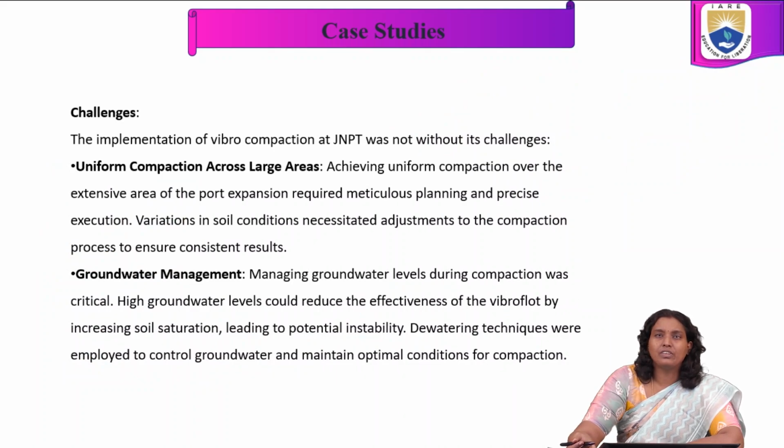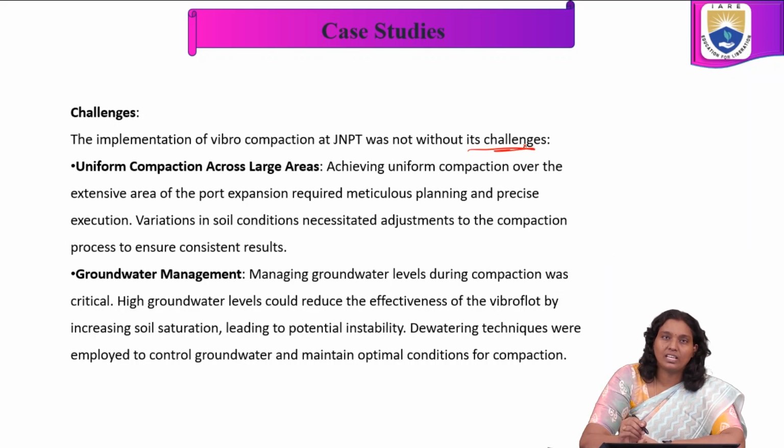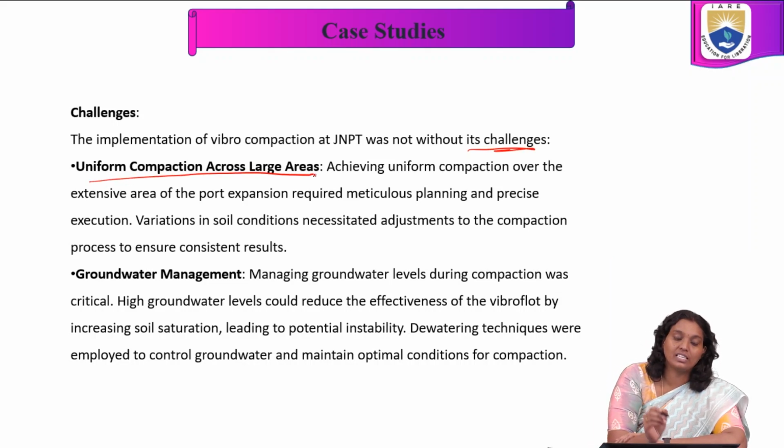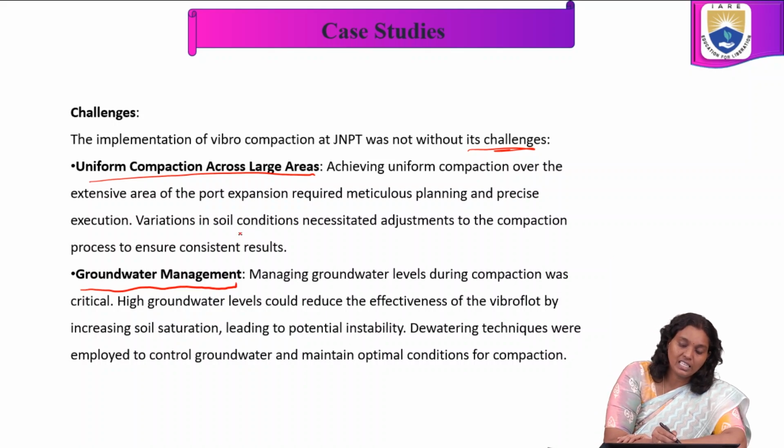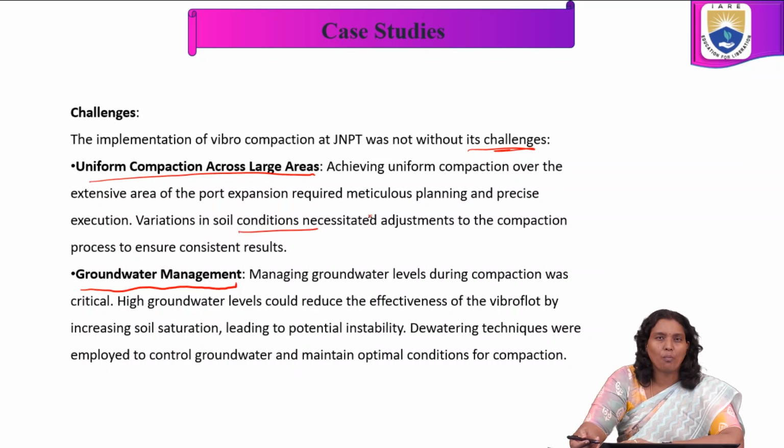In this, we may understand the challenges. The implementation of Vibro Compaction at Jawaharlal Nehru Port Trust was not without its challenges. That is uniform compaction across large areas, and also groundwater management. Achieving uniform compaction over the existing area of the port expansion required meticulous planning and precise execution. The variation in soil condition necessitated adjustments to the compaction process to ensure consistent results.